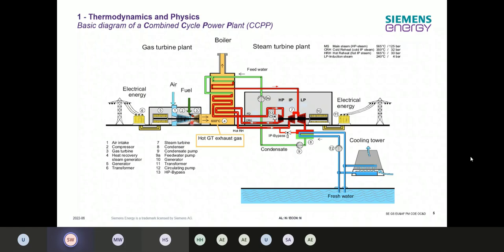And from there, we're getting through the turbine part of the gas turbine. The gas turbine normally has 4 blade rows where we're taking out the power from the fuel-air mixture, from our gas. In this process, the exhaust gas temperature is dropping.